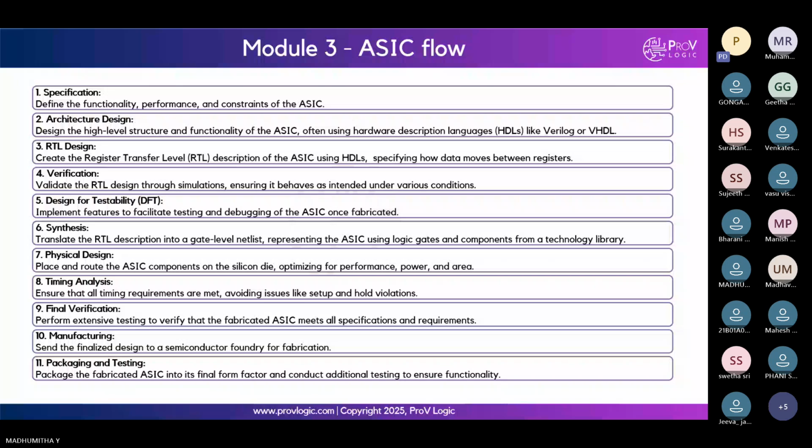So this is the order. Now, if you see points 6 to 9, this is what physical design is. This is the part of physical design, and this order must not be changed. Only when synthesis is done can we do physical design. You cannot go from physical design to synthesis. Once synthesis is done, only then you can start with floor plan. Once floor plan is done, only then you can proceed to power plan.